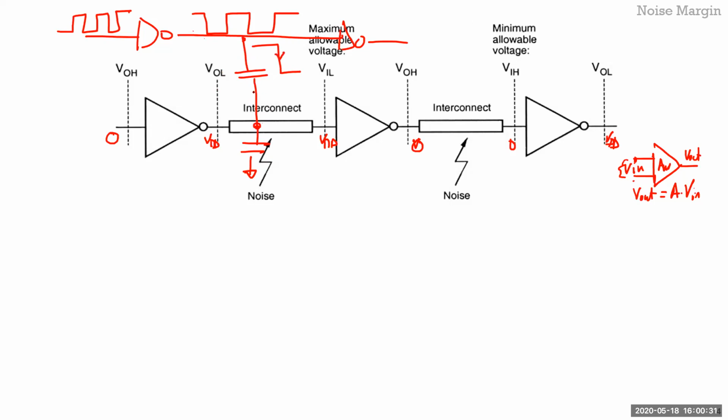So this is sitting at VDD, and when this node goes really sharp, everyone knows the current flowing through this is I equals C times dV over dt. So if dV over dt is really huge, that means there'll be a huge current flowing through it, which means it'll charge this cap, or discharge this cap because the current is in the negative direction. So this is sitting at VDD, and it'll immediately get a glitch, and then it'll go back to VDD, right?